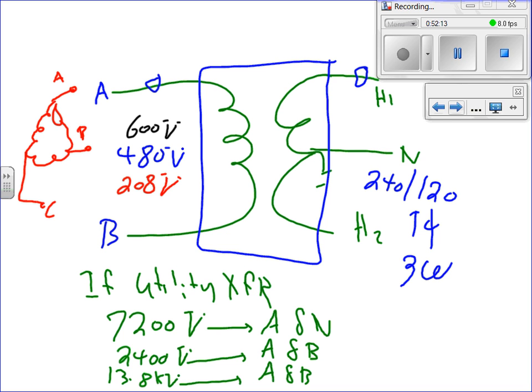But we could have these systems in our building, and we size based on the high voltage. We will go there when we do the industrial. Besides the transformer, if the voltage here is 13.8, how do you size the cables for 13.8? They're not 600 volt. We can't go to the same table now, can we? No. Any questions, guys? That will wrap up chapter 6, basically.